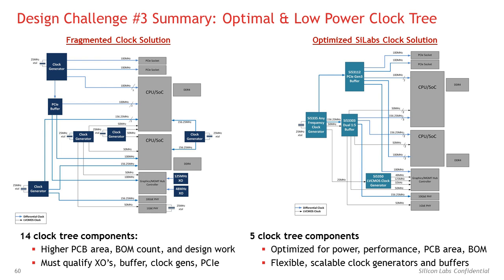Utilizing Silicon Labs programmable any-frequency clock generators, low-power PCI Express clocks and buffers, as well as our universal clock buffers, greatly simplifies clock tree design, all while meeting and exceeding jitter performance targets and reducing overall system-level power consumption. As shown in this specific example, we've reduced the number of clock ICs required on the Cavium ThunderX design from 14 components down to 5.